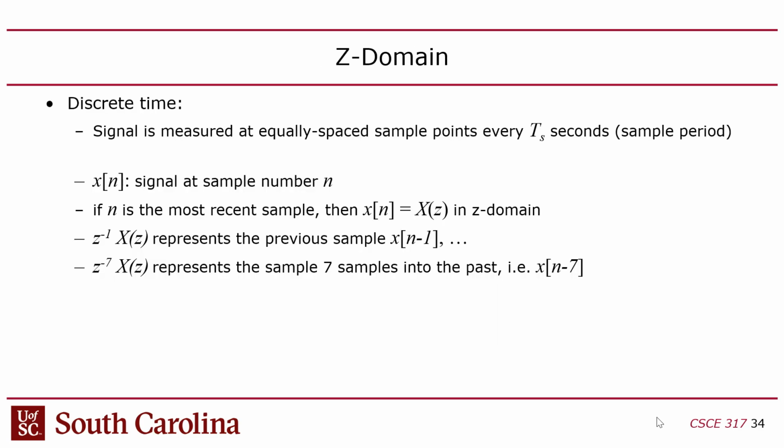Okay, so that's basic S-domain control theory. But the problem is that S-domain is continuous, and you can't actually build a continuous controller on a processor. It's impossible. You have to build a discrete controller. And so there's this whole separate concept called the Z-domain for discrete controllers. You can't actually build an S-domain system digitally. You can't build an S-domain controller unless it's an analog system.